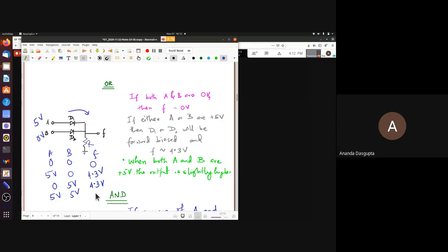Okay. So what will the voltage here be? Can anybody tell me that? If both diodes are forward biased, what will be the voltage across the resistance R? Somebody unmute and tell me what the output will be. Of course, because I'm calling it an OR gate, it's obvious that 1 0 should give you 1, 0 1 should give you 1, which we have already achieved, and 1 1 should give you 1. But when I say 1, how much is it? 4.3. Okay, it looks like it's going to be 4.3 volts.